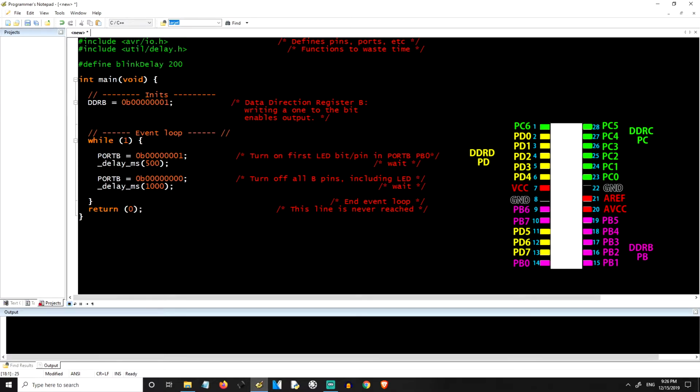There's other ways to do it, like you can have a header file that you include up here, and you can call it whatever you want. You can say, you know, like pin layout.h, and you can include it, and I'll show you how to do that later.